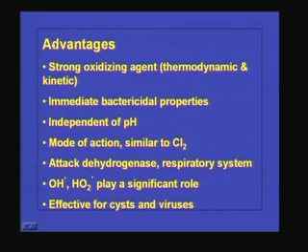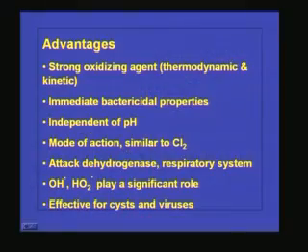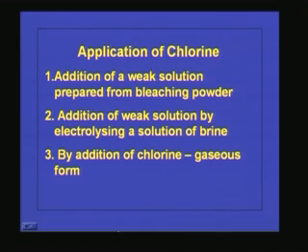The advantages of ozone are that it is a strong oxidizing agent, it has immediate bactericidal properties, and it can work at any pH, because we have seen that chlorine works only in the acidic range, but ozone works under any pH condition. Its mode of disinfection is similar to chlorine, attacking dehydrogenase and the respiratory system. When ozone reacts with water it produces hydroxyl radicals and HO2 radicals, which play a significant role in disinfection, and hence it is effective against cysts and even viruses. But again, it does not have any residual property.